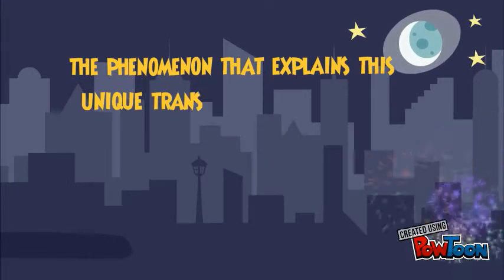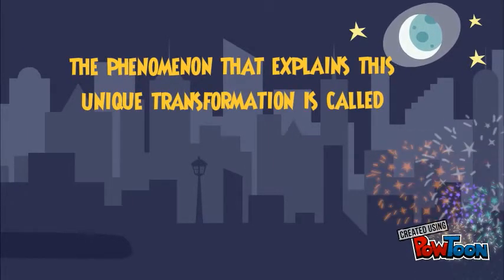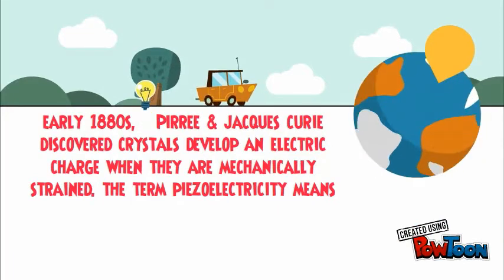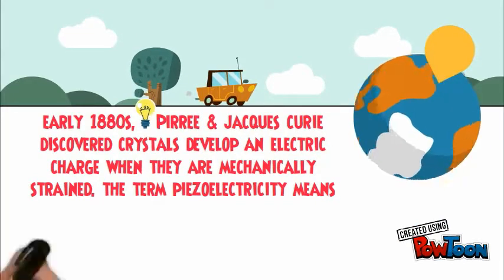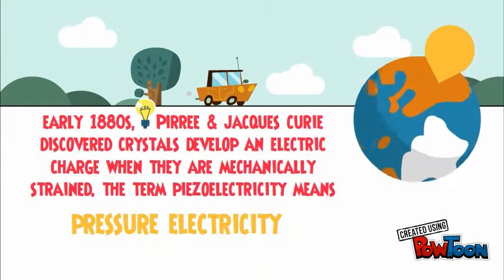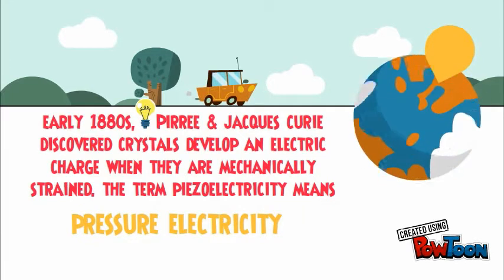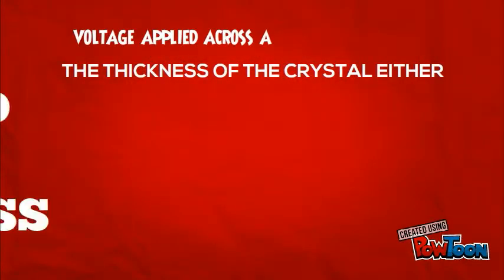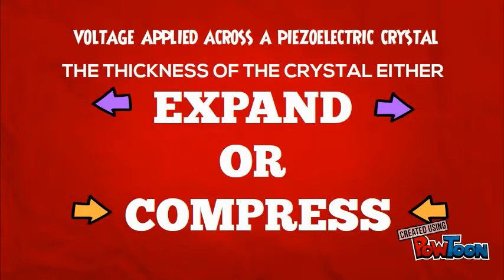The phenomenon that explains this unique transformation is called the piezoelectric effect. In the early 1880s, Pierre and Jacques Curie discovered that certain crystals develop an electrical charge when they are mechanically strained. The term piezoelectricity means pressure electricity. When voltage is applied across the piezoelectric crystal, the thickness of the crystal either expands or compresses depending on the polarity of the voltage and the molecular configuration of the crystal.